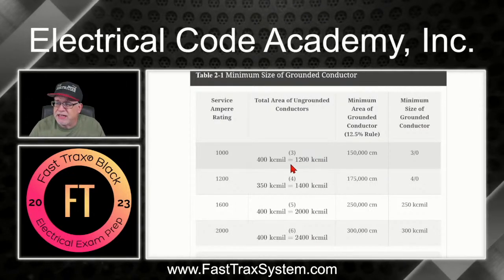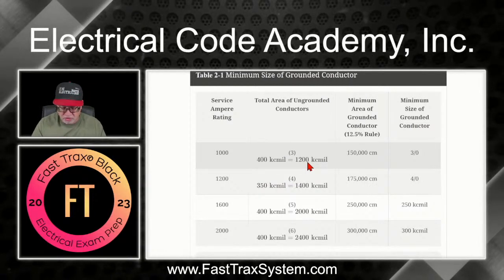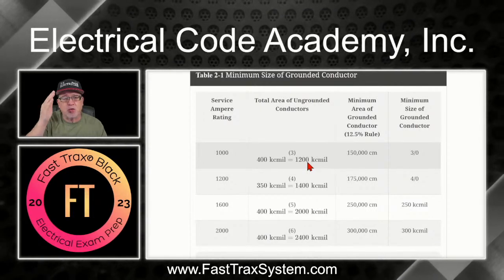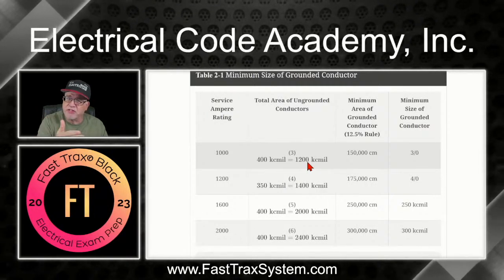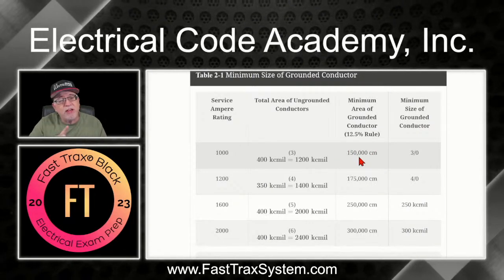So we'd have to take that 1,200, which incidentally is 1,200,000 circular mils, or you can take 1,200 times 1,000 and that's how you get your 1,200,000 circular mils. And we multiply that by 0.125, which is the decimal equivalent. You can take the 12.5 and move the decimal two places to the left to make it a decimal, which is just much easier for your calculation. And that's going to end up being 150,000 circular mils.